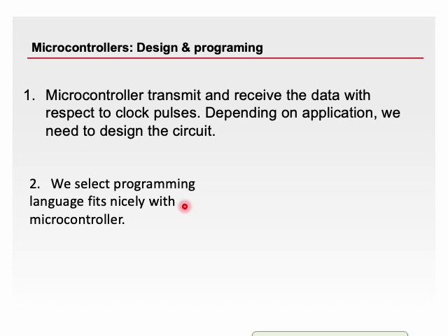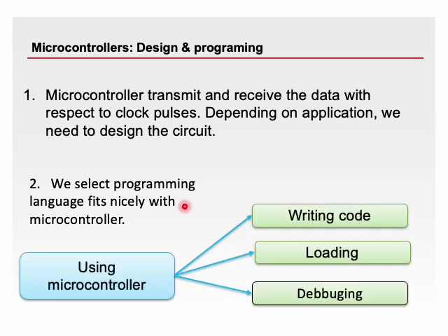After this step, it's time for the software activities. Programming a microcontroller involves writing code in a programming language such as C, C++, MicroPython, or assembly, and then compiling that code into machine code that the microcontroller can understand. The compiled code is then loaded onto the microcontroller using a programming tool such as a programmer or bootloader.